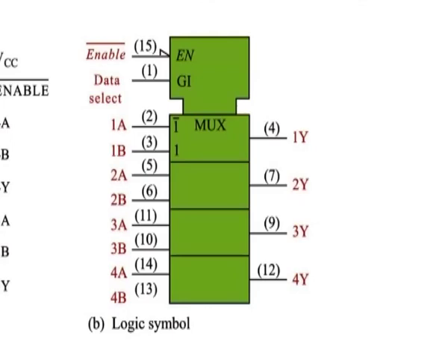All labels within the upper multiplexer block apply to the other blocks below it. Notice the 1 and the 1 bar labels in the multiplexer blocks and the G1 label in the common control block. These labels are examples of the dependency notation system specified in the IEEE standards. In this case, G1 indicates an AND relationship between the data select input and the data input with 1 or 1 bar labels.